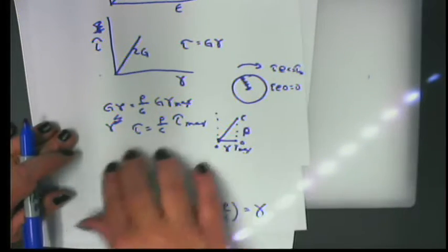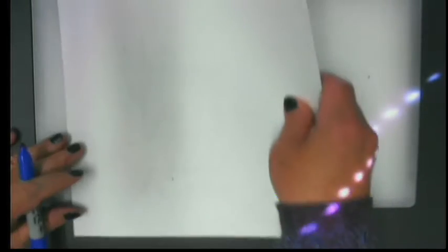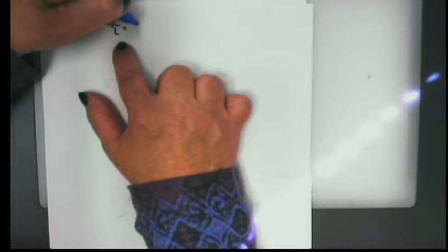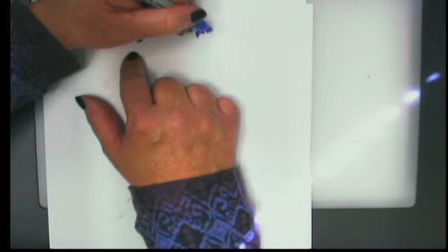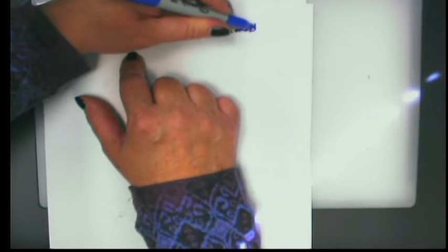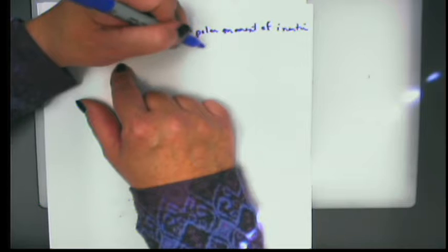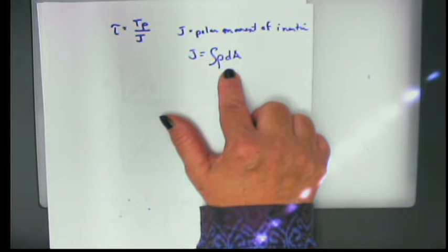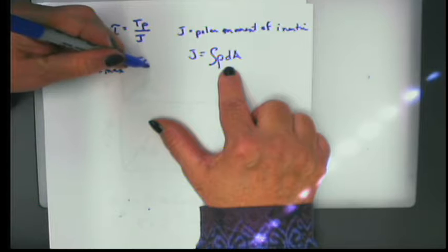All right. Since we have 4 minutes left, in the interest of time, you can bring these equations together in a useful form. What we have right now is only useful in understanding the geometry so that we know what we're talking about. But basically, tau is equal to torque times rho, the distance from the center, over J, which J is the polar moment of inertia, which are tabulated for circles and other common shapes in the back of your book. Basically, it's equal to the integral of rho squared dA. You may or may not remember that from statics, but also tau max then is equal to Tc over J.